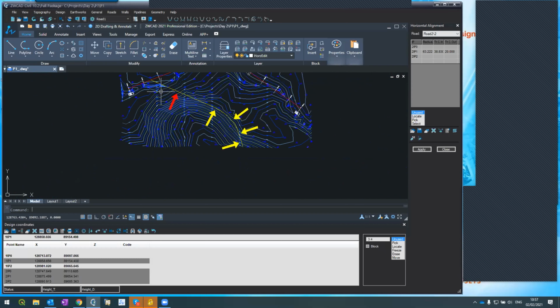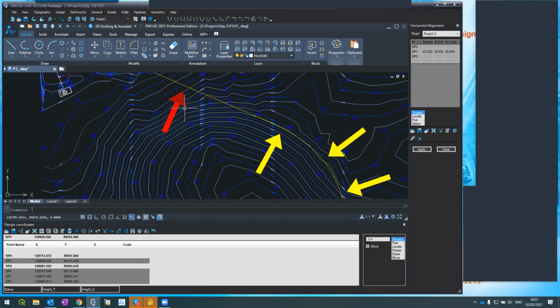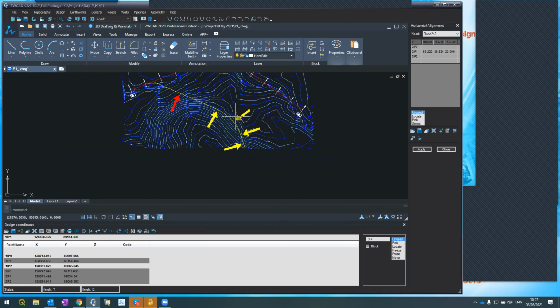The software took the entire segment and created the road out of it. This is the beginning point of the road. It starts with red, then the rest of the element with yellow. And here we see the data. It starts with first IP, second IP somewhere here, I don't know, we'll see it in a minute. Radius of 63 meters here, sorry, here.